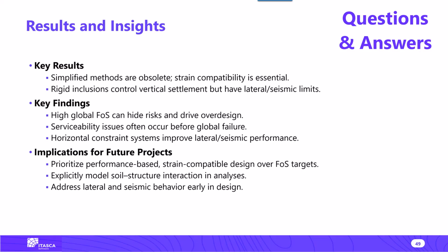Okay, we have a question, Augusto, in the chat. I'll read it. In the presentation, it was shown that the cage reinforcement and concrete pile properties were assigned separate elastoplastic material models. Can plastic rotation outputs still be obtained in the same way in this case? The plastic rotation, plastic strain.